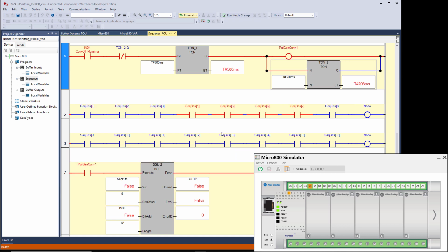Well, actually I left it on a little bit longer, but you see it's kind of hard to look at because sometimes it looks like 3, sometimes it looks like 4. But this gives you an idea of how you might track parts on a conveyor. Not track what it is, only that there's something there. Because remember, photo eye 2 just sees something at that one position on the conveyor.